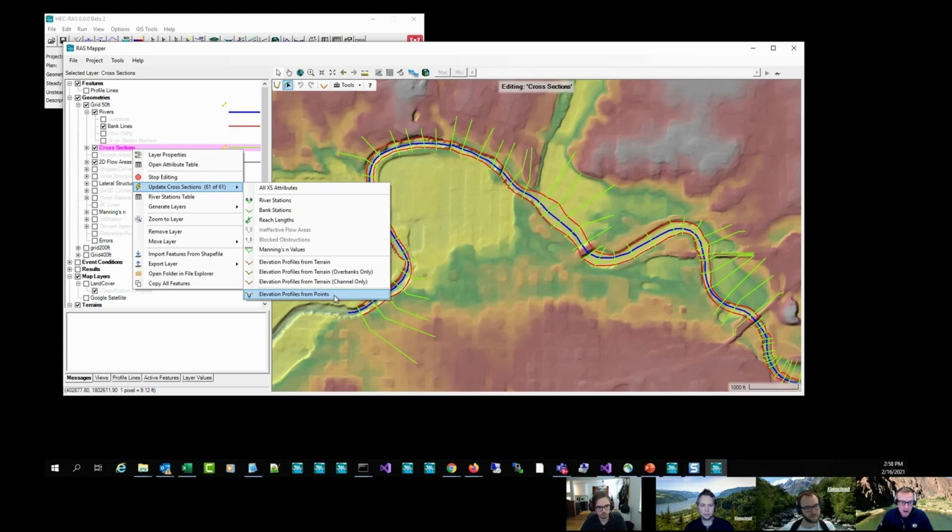But if you've got that bathymetric data from the drunken boat driver across the river, you can lay out your cross sections and extract elevations. We've all had cross sections like that. Yeah. So that's a great way to extract elevations. It's a great way to include bathymetric data into your terrain model.